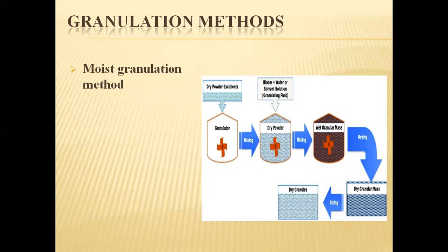Generally, this method is the most widely used method in granules preparation. A binding agent is used along with diluents, other excipients, and part of disintegrating agent, which are moistened together with the help of the binder solution to make a coherent mass of powders. Then the coherent mass is passed through a specific sieve number, generally sieve number 8 or 10.